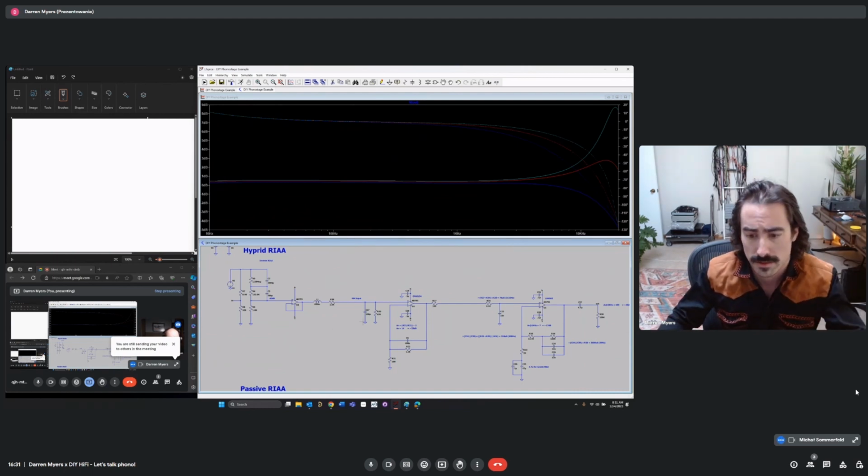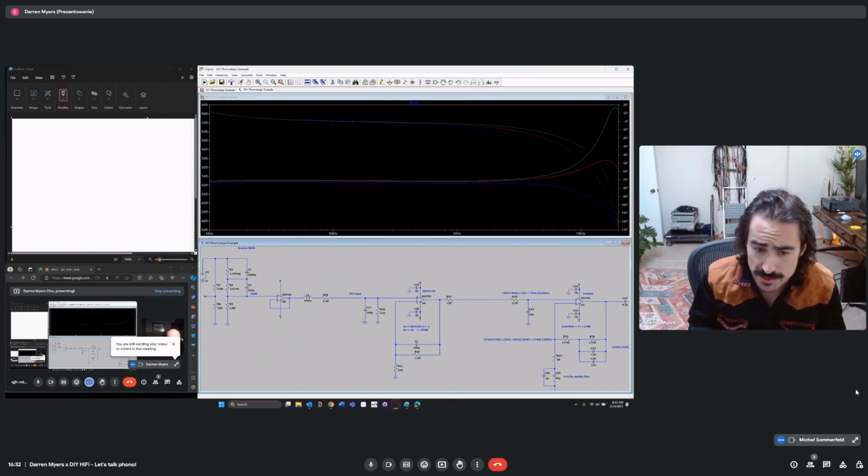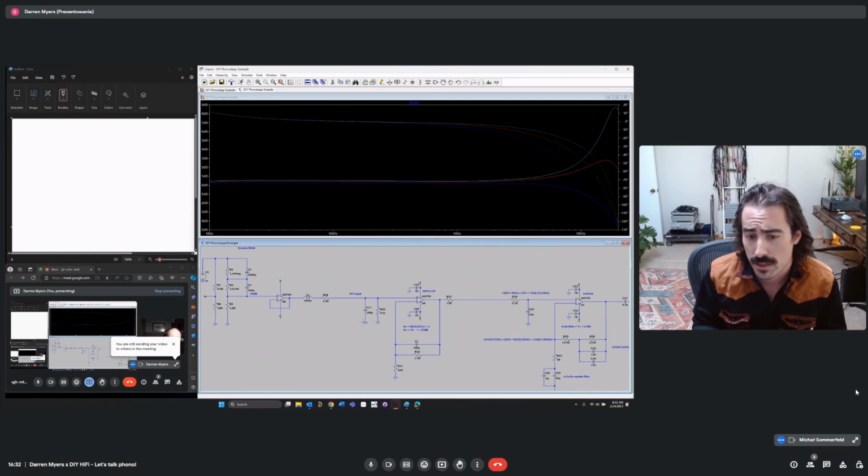So start with capacitors, because we have the cable which we won't be changing, and try to get the capacitors in the ballpark of what the cartridge expects to see, and then tweak the resistance. The manufacturer usually specs a certain resistance that they want you to load it at.